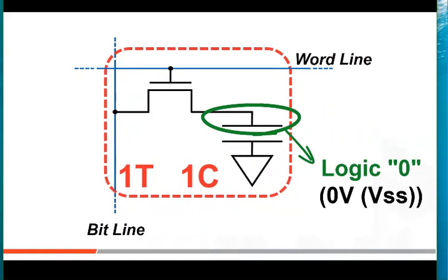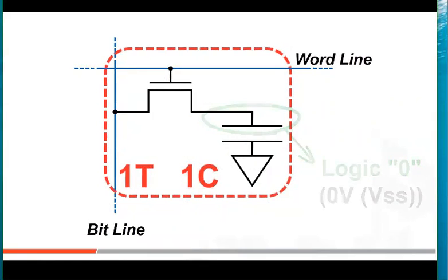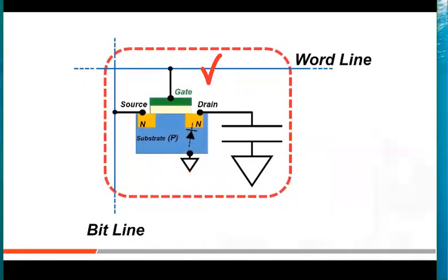Note that this MOS gate switch here sits over a substrate that is connected to either power or ground to make it work. Again, we will use VSS or ground in our video. Even with this gate off, there is a path through this reverse diode junction.